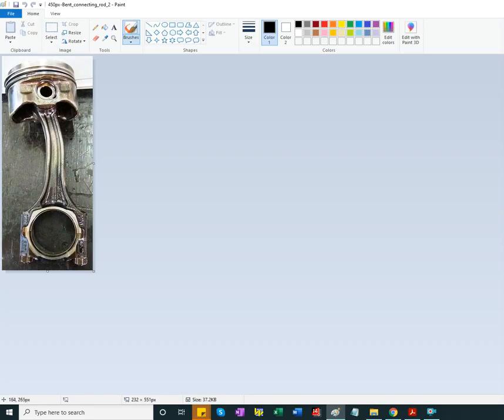Regarding the connecting rods, I would point to the way they are supported at the ends. So this connecting rod buckled in the transverse plane, and as you can see, here was the crankshaft, here's the piston pin, and the slope of the bent connecting rod is non-zero. Let me be more explicit.